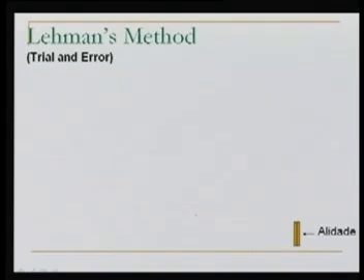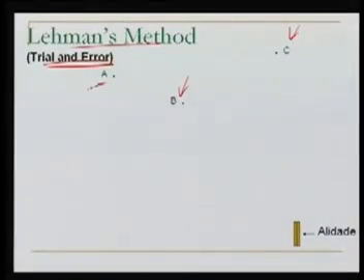Well, there is one more method, which is the Lehmann method. Again, it is a trial and error method. What we do in this method, same thing: three points there on the field, which are the control points. We know their location. These capital A, capital B and capital C, which I am showing you, could be anything. The condition here is we should be able to locate them. You carry your plane table, put it there, and then we look around for the control features, which are also plotted on the plane table. Having located those, we start this process of the three-point problem. We solve the three-point problem in order to do two things: orient our table as well as find where we are.